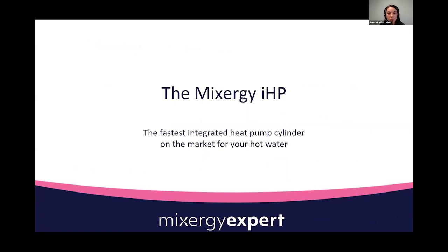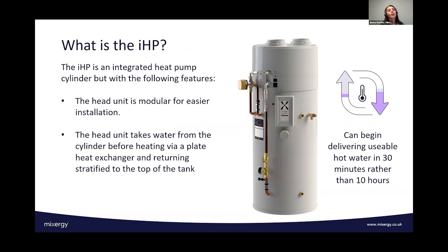And now I'm just going to tell you a little bit about the Mixergy IHP. This is an integrated heat pump where the head unit is modular for easier installation, and the head unit takes water from the cylinder before heating via a plate heat exchanger again, and returning stratified water to the top of the cylinder.